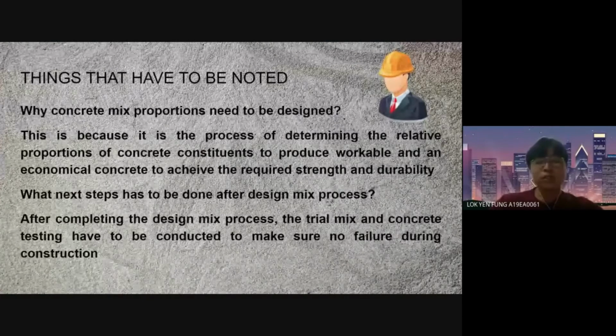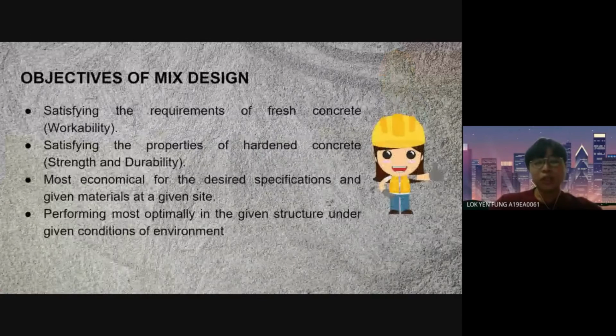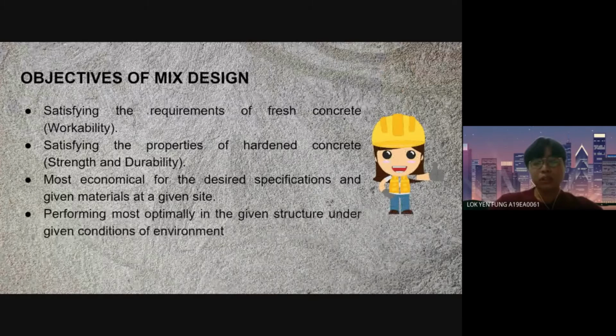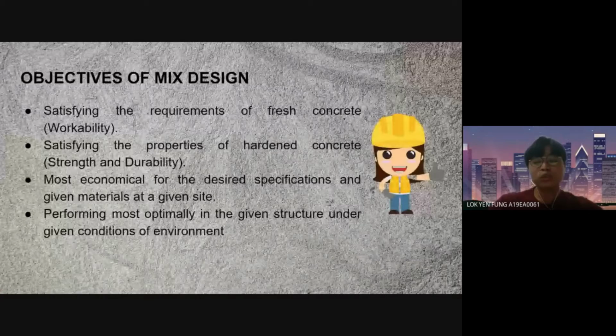The next step after the design mix process is that the trial mix and concrete testing have to be conducted to make sure there is no failure during construction. The objectives of mix design: satisfying the requirements of fresh concrete, which is workability; satisfying the properties of hardened concrete, strength and durability; being most economical for the desired specifications and given materials at a given site; and performing most optimally in the given structure under given conditions of environment.